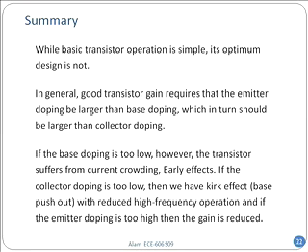But then I have this problem that as soon as I try to pump up my emitter current so that I have good gain, the electrons go through and overwhelm this depletion region. And very soon the depletion charge is equal to the electrons that are flowing in. And so there is no charge to balance the base charge. Base gets pushed out and you have a wider base width. You're supposed to have a very thin base for good gain. Your effective base now is all the way up to the subcollector region, which is a horrible transistor. So that is the trouble.